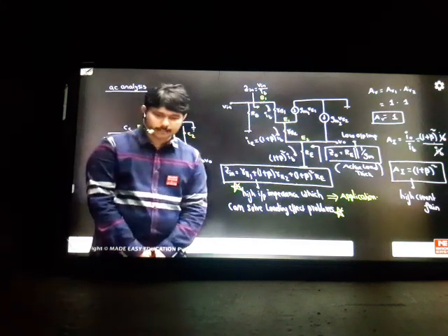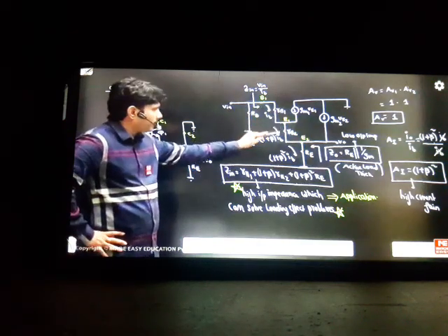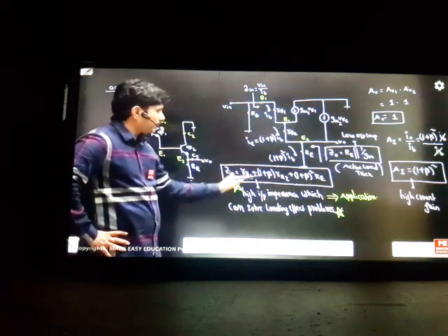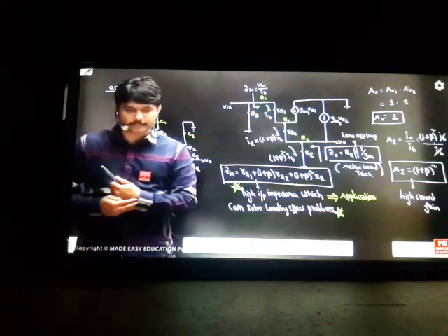So Parthasarathi, there is no input impedance formula here. Take the first impedance R1. For the second impedance R2, IB has an extra 1 plus beta multiplied, so that factor is increasing. And if you go for RE, I multiplied 1 plus beta square to get the input impedance.